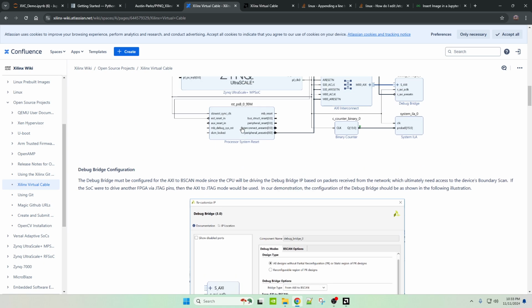The way they do it is they use a generic UIO driver to access the memory region where the IP resides. In our case, what I've done to the code is I've made it so that it memory maps directly to /dev/mem. So it uses the full deal, and then I just use an offset to the physical address.